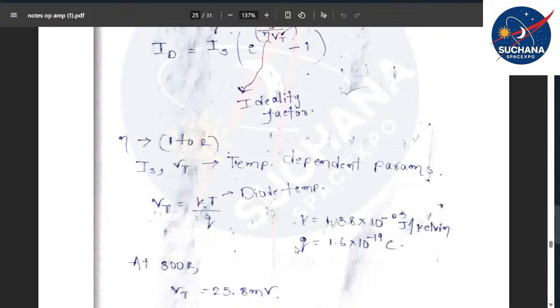If you just blindly believe in that, see, we have already taken the case study of operational amplifiers and discussed slew rate. For those people who don't know about slew rate, for example, I have chosen one kind of op-amp which has some slew rate, and you have made a PCB with another op-amp having some other slew rate. So you should not expect both PCBs to give the same output. In the schematic everything is the same other than the op-amp that we have used. Maybe I have used LM741 and you have used something from Linear Technology.